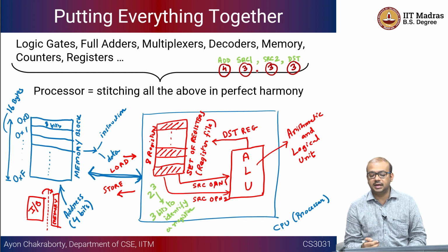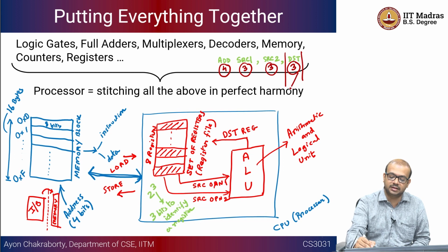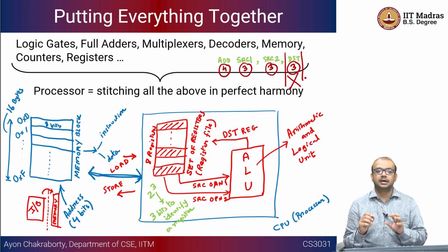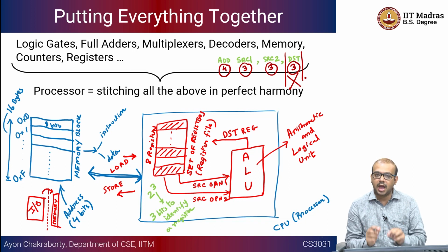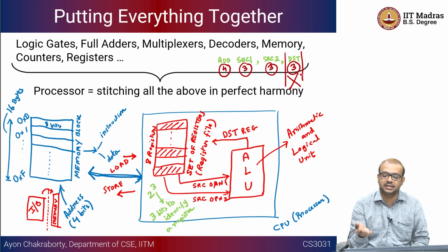So, if I rather say that I will not have a separate destination register, this flexibility is going to be gone, but I am always going to say that the value is going to be available in a default register, and the default register could either be SRC1 or an accumulator, which is neither SRC1 nor SRC2. But this information is not passed from an instruction perspective. The instruction does not explicitly specify where the value that is going to be computed is going to be stored. The destination register is implicit, not explicit. In that case, of course, I do not have to save these 3 bits.